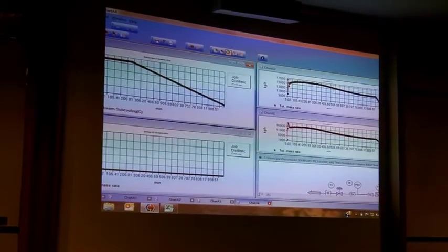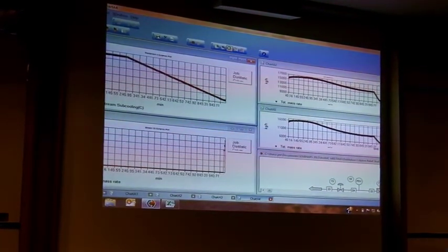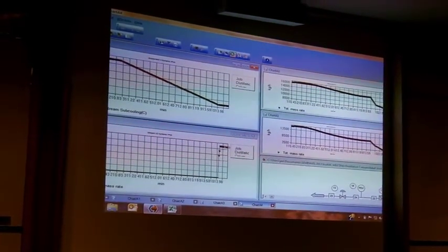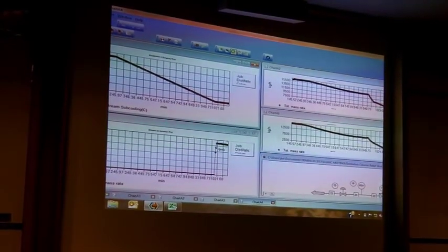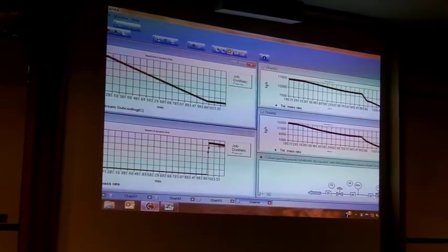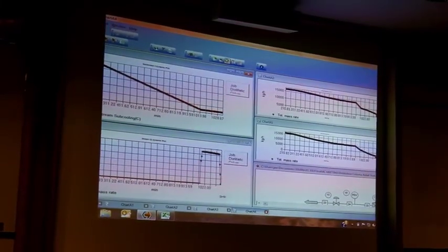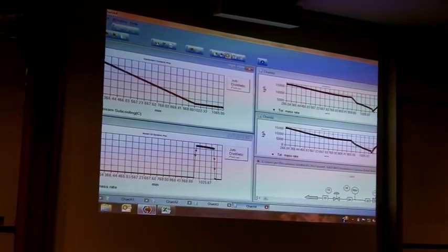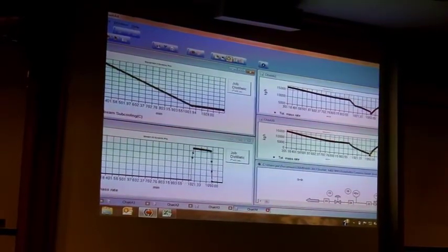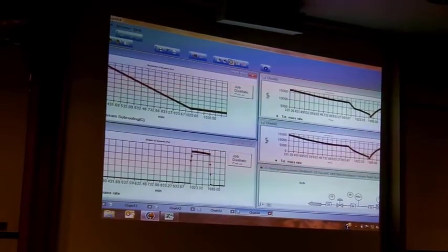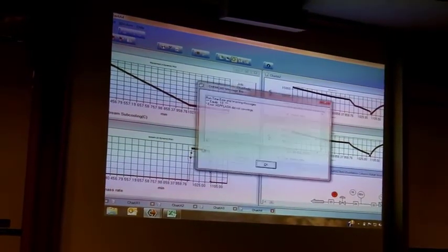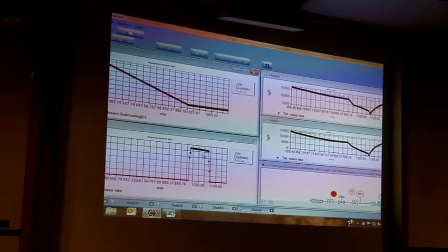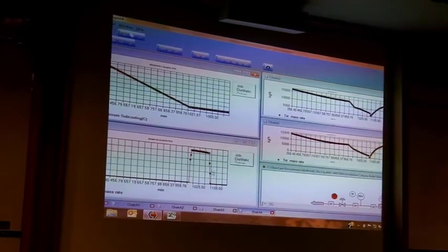So it's nice. There's the column pressure building up now. So the overhead flow has dropped off. There's the relief valve lifted. Now it's going to reseat. And then the column's going to start to recover. And that's the end of the simulation. That isn't real life, that. The lifting of this, I've controlled that.